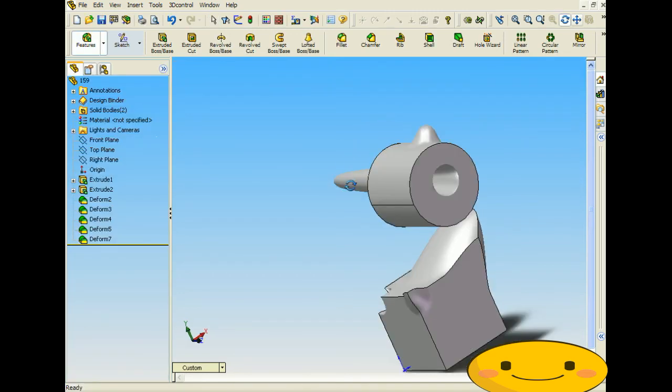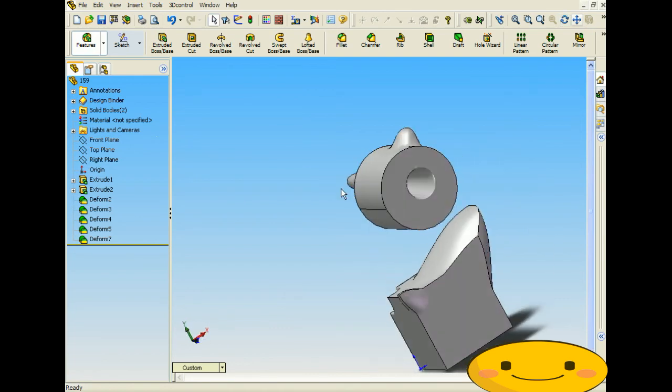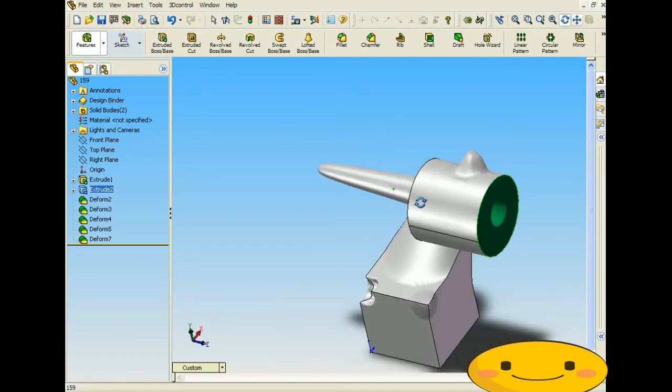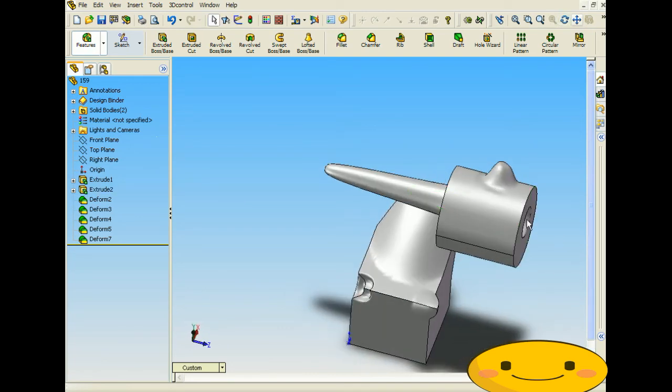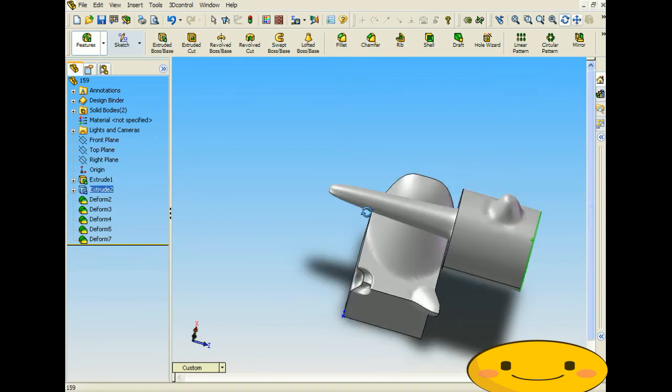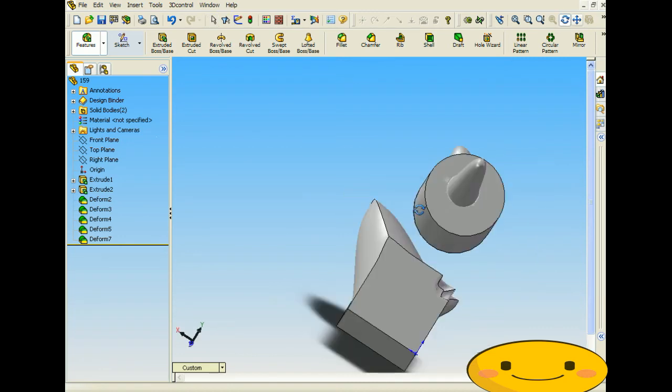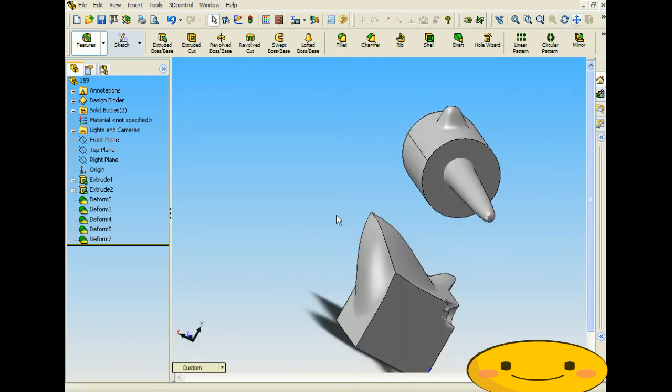You can see that as we pulled that through, it's deformed through the back. There's a correlation between how much is pulled through the back and through the front. If you look at the deform we pulled out and what's pulled out of the back too, you can see that they kind of jive together, and as you're pulling it out, it's kind of pulling out from the back too. So that concludes our tutorial on how to use the Point Deform feature within Solidworks.